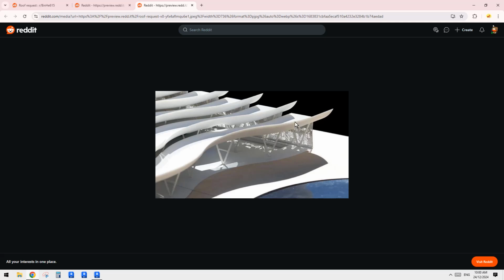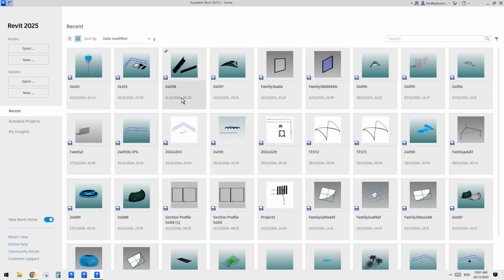Of course, if you want to do it manually, you can do a model in place and do a sweep, right? But it means you need to do individual ones, maybe copy and paste, and then if you need to change it slightly, you need to go back and model them, adjust them. But if we do a railing, it can be very easy, and we will also include these support structure columns in that railing family.